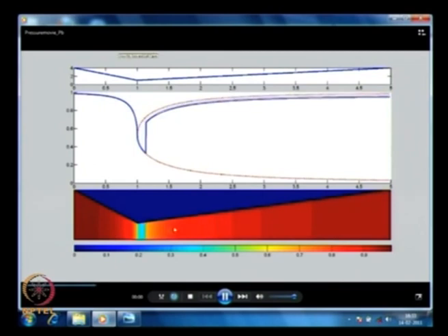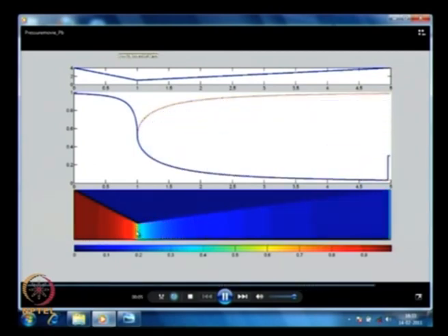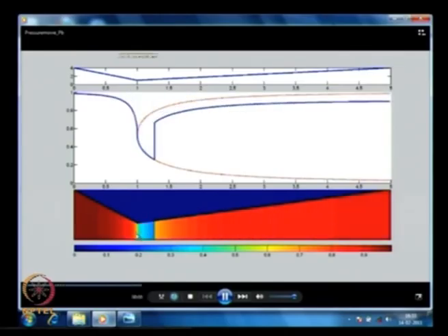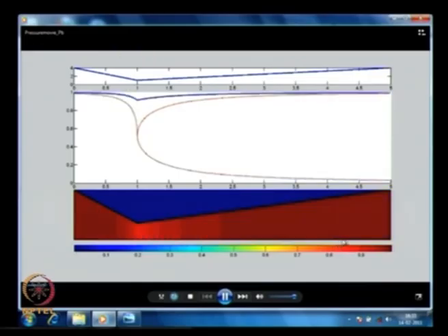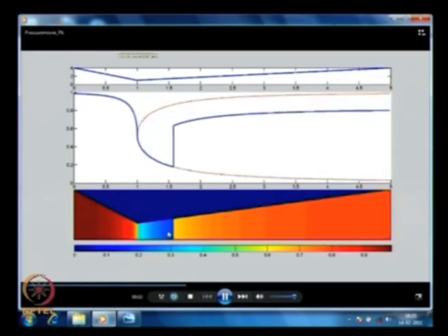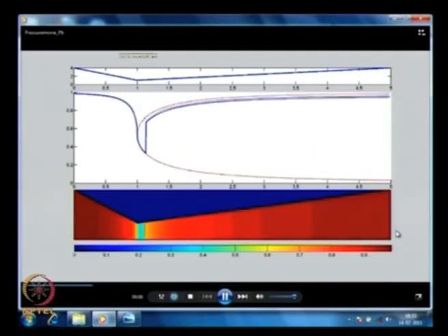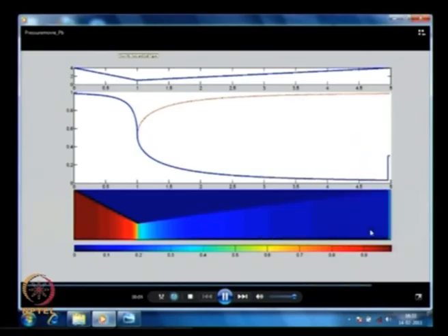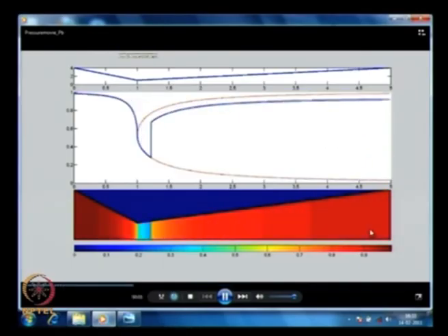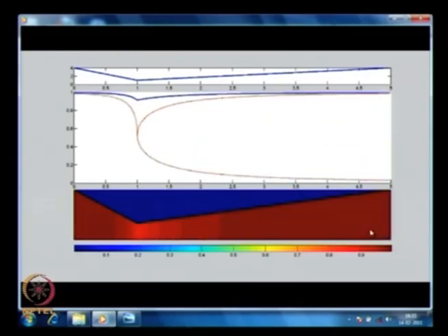We start with fully red, which is almost no flow, and then it is becoming more and more low pressures, the center becoming supersonic. That blue is all supersonic conditions, very low pressures, and the shock, this jump is the shock really, and that is moving more and more downstream. Okay. This is one nice thing. We can of course plot other things like temperature, Mach number, everything similar, they all look the same almost.